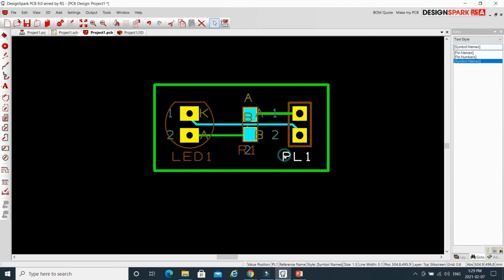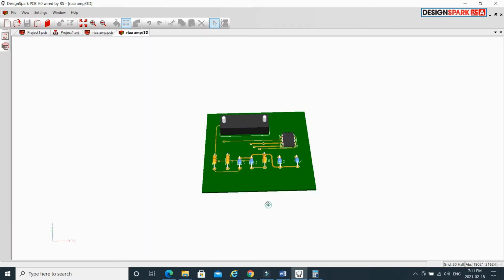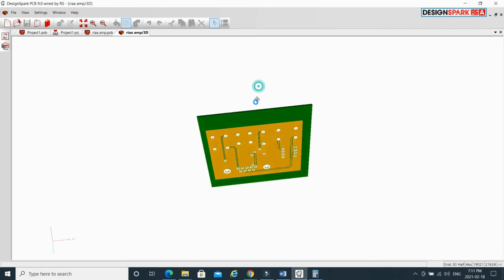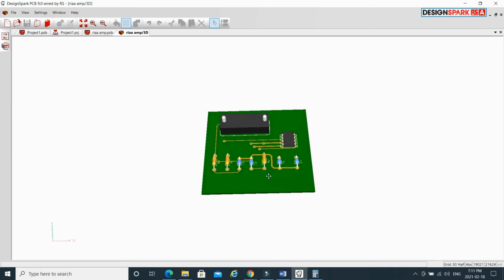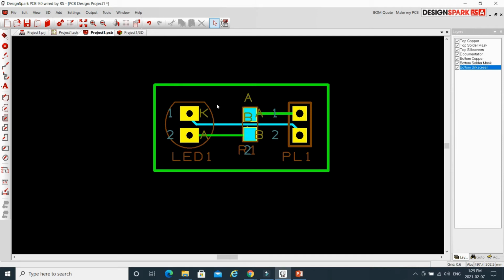When dealing with applications that require electromagnetic shielding or heat dissipation for components such as power transistors, it is useful to include an additional copper surface on the PCB called copper pour. Copper pour is a conductive surface which, when connected to the ground, can provide additional shielding. And when connected to the thermal pad of a component that generates heat as a byproduct, it can help to dissipate heat. Therefore, copper pour is very useful in many PCB applications.